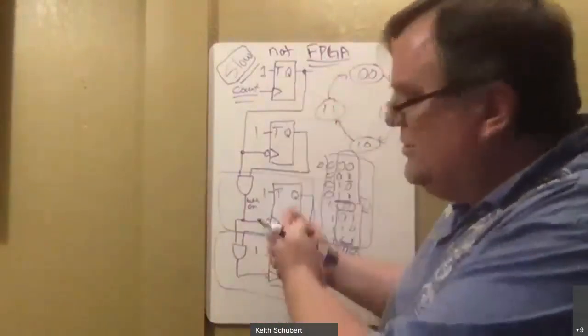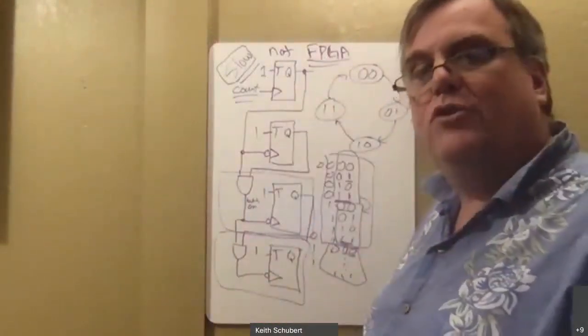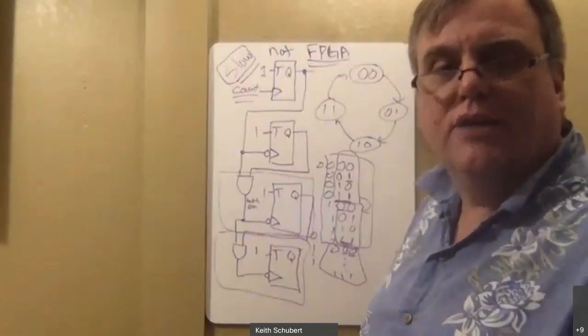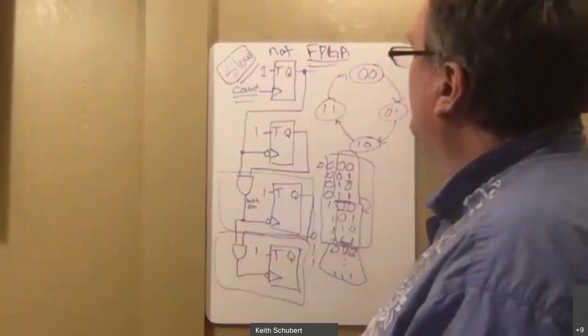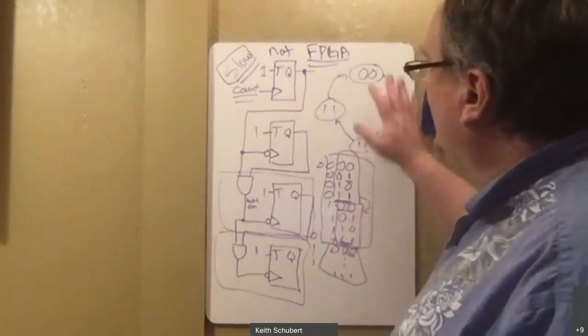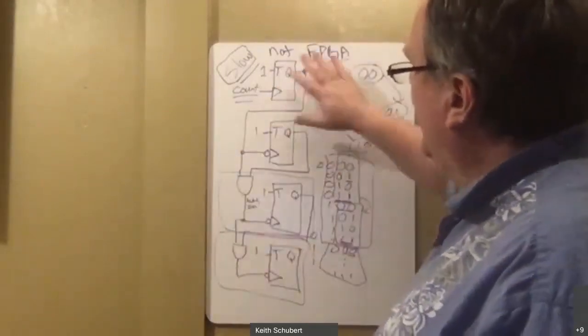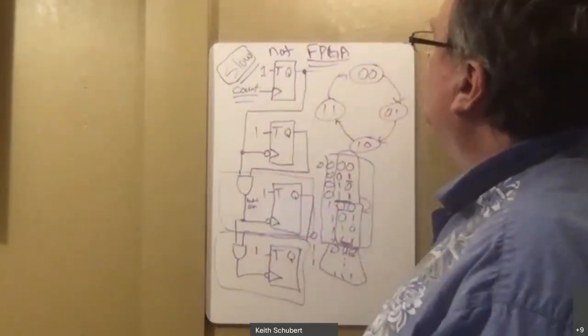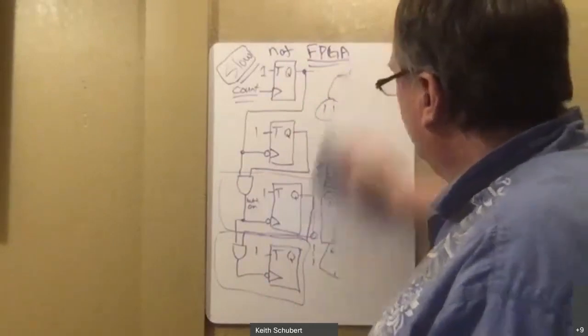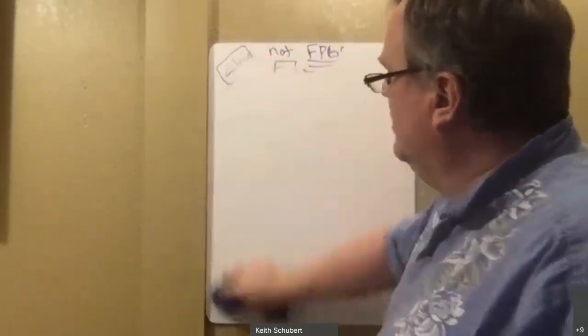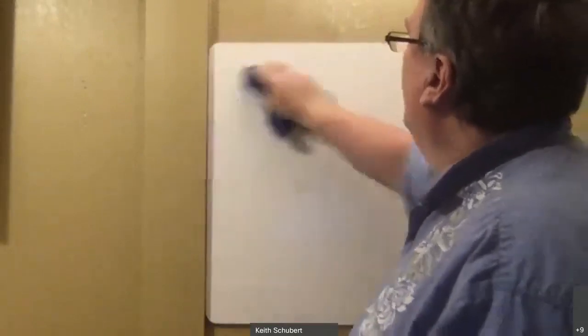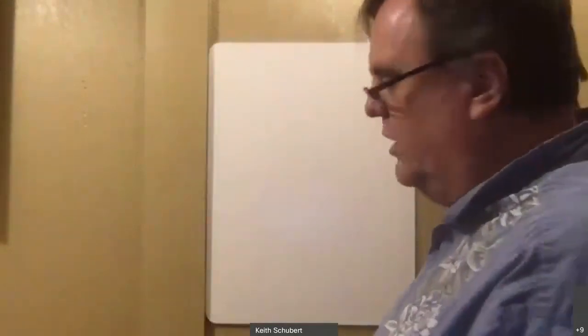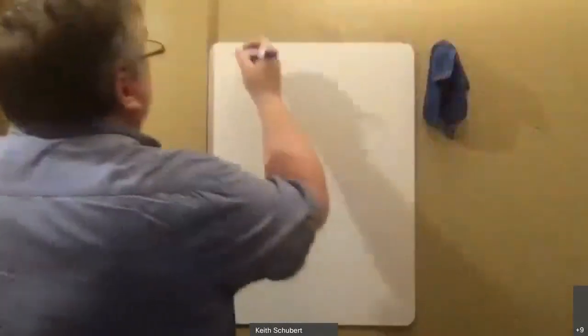But my circuits aren't base 10, so therefore I have to do binary coded decimal. I can't do regular binary numbers. I have to do BCD numbers. And this type of sequence, I can't use exactly this for it. It's a little more complicated. So let's take a look at how we can do a ripple design for a BCD. And remember, this is just slow, not FPGA stuff.